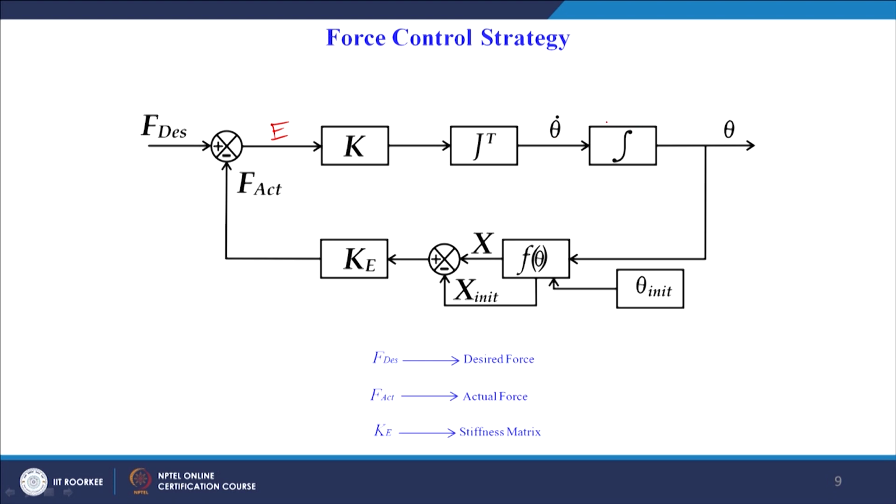So, the joint velocity is integrated by the Runge-Kutta approach, which is the fourth order method, to get the joint variable theta, so that through forward kinematics we obtain the actual position of the end effector of the index finger exoskeleton with the deformed position, the initial position being also obtained with the initial angle given to the forward kinematic model f of theta.